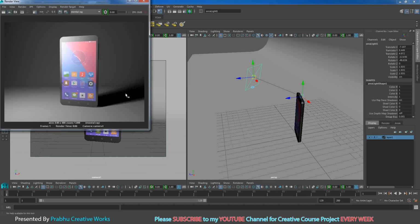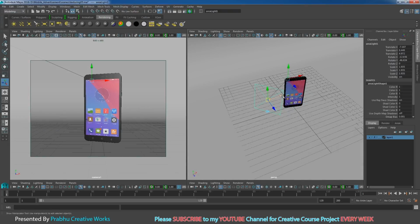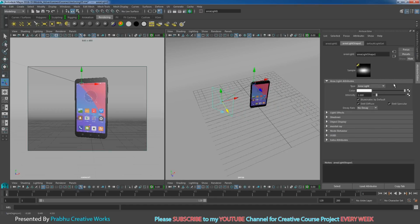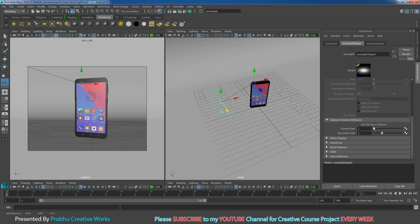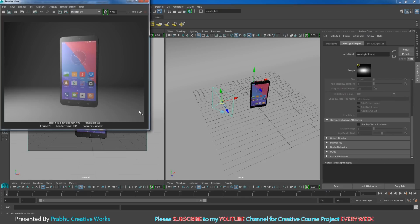I want to turn off the shadows in my output. So I will select my area light and move it a little bit to this side. Go to the attribute editor, and go to shadows. Here you turn off ray trace shadows. I click on this one and click render. Now we didn't get any shadows for our scene. So this is what we want.